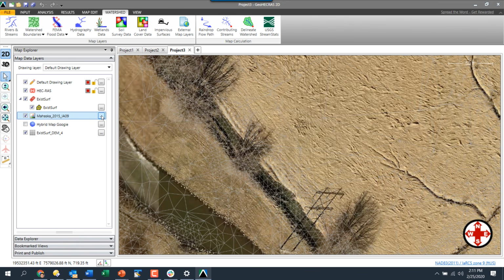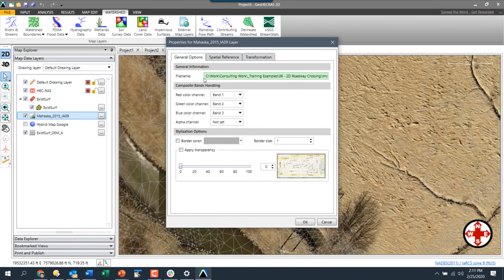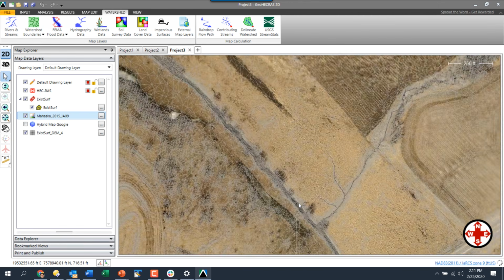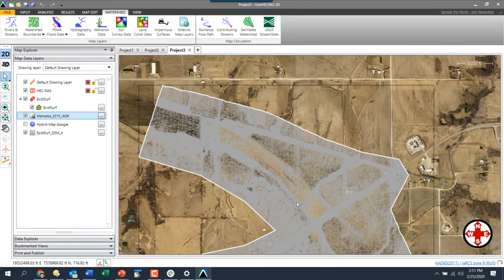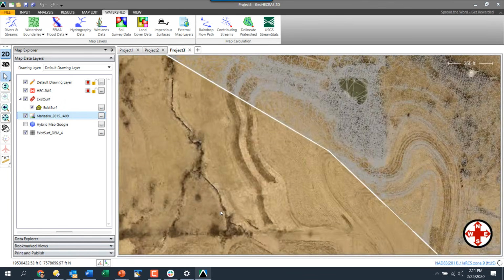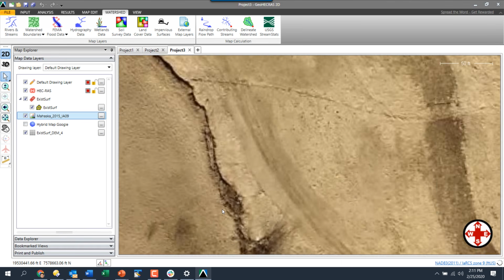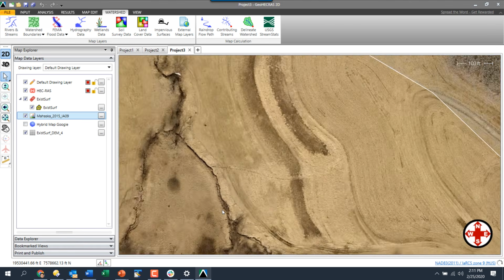Okay, and we can check that imagery as well. And so everything's in there. It doesn't tell us the pixel size, though. Unfortunately, it doesn't give that information. Because ECW files are multi-pyramided, meaning that as I zoom out and zoom in, it'll use a different image. So it's a pyramid file, so as you zoom into more detail, it'll pull in up to the maximum resolution it has.